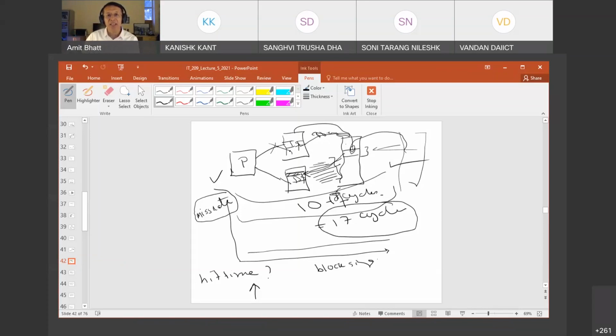So instruction cache only has read operation. This is conceptually very important. A processor does not go and write something into your program or change an instruction. That was done by the compiler, if it found it suitable, but not by the processor. So for any write operation, the instruction cache is not involved. It's only in the data cache.